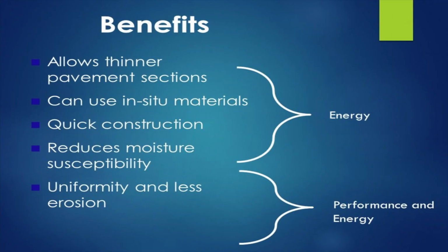Some of the things that you'll find, the benefits of the reclamation process, as we close here, things to think about. Obviously, they're thinner pavement sections. The strength of the reclamation has a very high structural value for what it is, and you're recycling. Now, it's not a typical CTA or CTB that we're all familiar with.